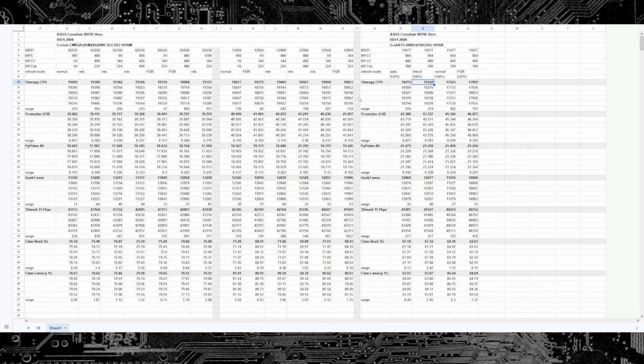Now, when you start overclocking, things really level out a lot, because as it turns out, when your refresh interval is 65,000 clock cycles instead of 11,000 clock cycles, it doesn't really matter that much how long your refresh cycles actually are.